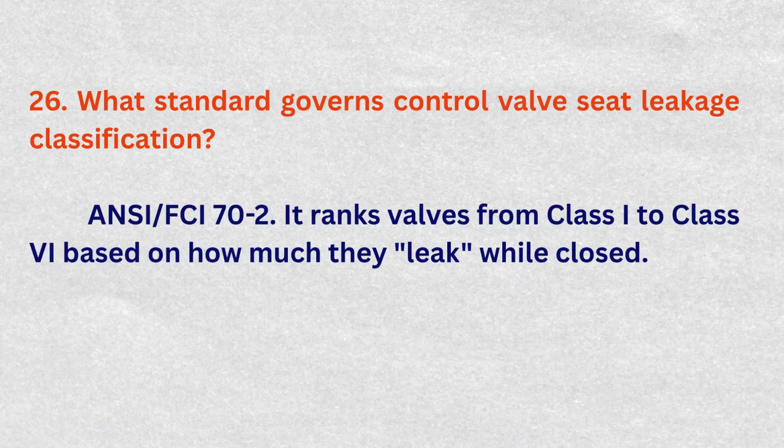What standard governs control valve seat leakage classification? ANSI FCI 70-2. It ranks valves from Class I to Class 6 based on how much they leak while closed.